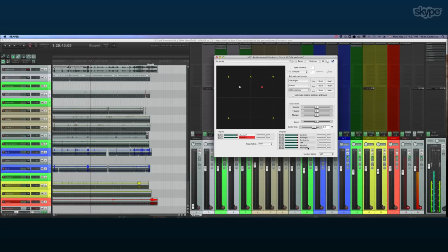Then I went through my studio and took my noise meter and calibrated all of them, so all of the speakers were sending out the same amount of pink noise when I went around and measured each one. The sub was tough because I wasn't really sure. It's putting out so much low energy and I'm rolling off all the highs. But I think I overestimated that it was too loud, so I brought it down even more, because the last thing you want is your bass speaker exploding in the theater, ruining the whole movie. So I went with caution and dropped it an additional 6 dB after it checked out right on the meter.